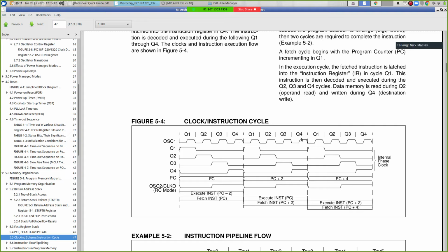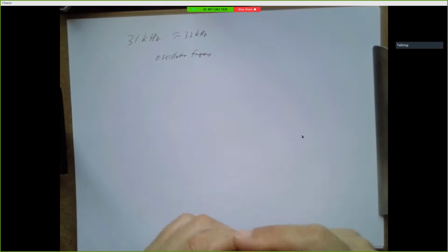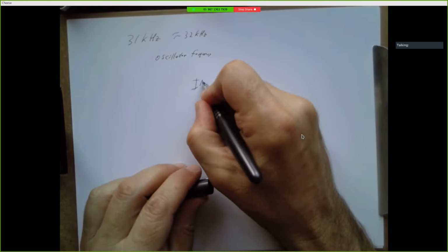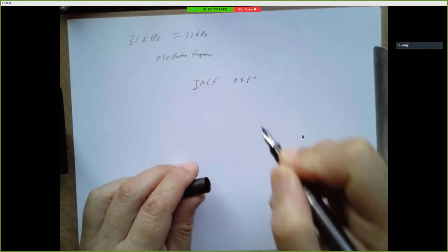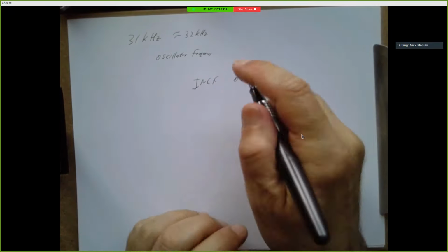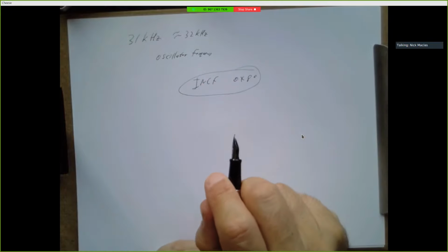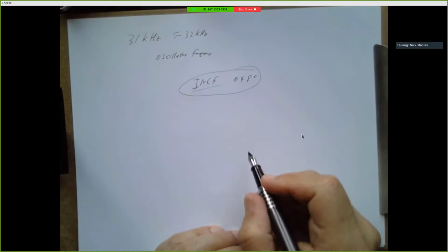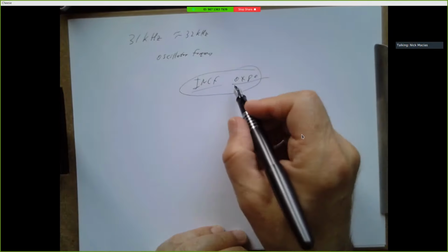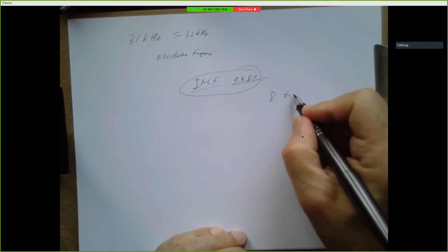And then another 4 instruction cycles are required to do the decoding and executing of the instruction. So one instruction actually takes 8 instruction cycles to execute. A typical instruction like increment file register 80. So 4 ticks to pull this instruction, the ones and zeros, out of memory. 4 ticks to say, hey, it wants to do an increment, read this location, modify it, write it back. Total of 8 ticks.